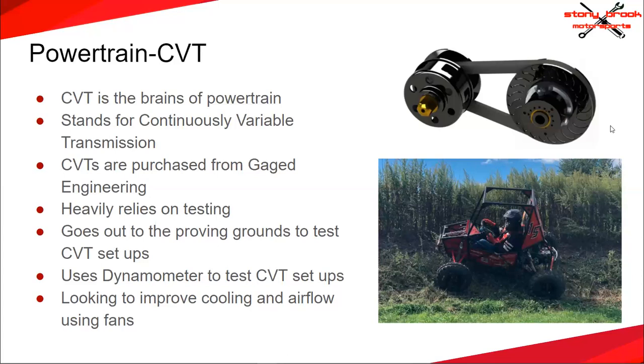Okay, so back to testing. Testing on this CVT, we have two ways of testing primarily. We use a dynamometer, which basically means throwing a CVT onto a motor and a generator and figuring out what the torque curves look like. Or we could take this out onto the field on the car and actually test it, which they do a lot. They do both of them a pretty decent amount of time.